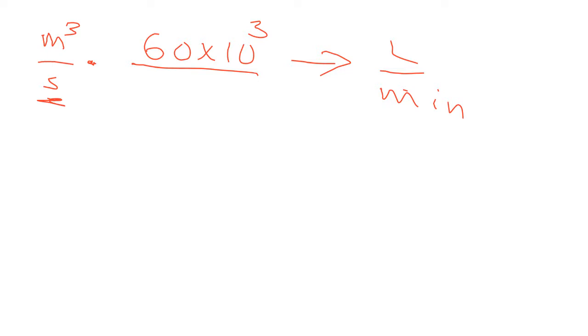And of course, some of you are also saying you have to take the average of the flow rate because it fluctuates, like 4 different values or 3 different values. Yes, that is important. And you have to either increase the flow rate gradually or decrease it gradually. So all these are precautions that you need to express clearly.